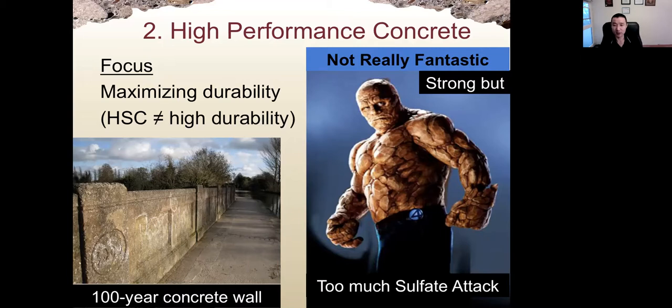And from the lecture on drying shrinkage, we know when we reduce the pore size, the shrinkage stress will be higher due to the Kelvin-Laplace equation. And also for high-strength concrete, the water amount is limited due to self-desiccation, or drying internally due to hydration. Because of these two reasons, high-strength concrete tends to have very high autogenous shrinkage, and if they crack, the durability will be lower.